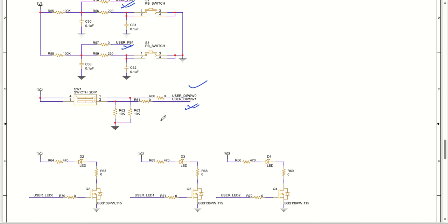So these two pins are capable of generating 00, 01, 10, 11 states. These four states can be generated by these two pins. What is going to happen is, this is the right side, it is closed. As you push it to the right side like this, 3.3 volt will appear on that particular pin. Similarly, if we push it to the left side, it will become open circuit. So it is grounded, which means you will see 0. So based on these two pins, you can generate a total of four state options.